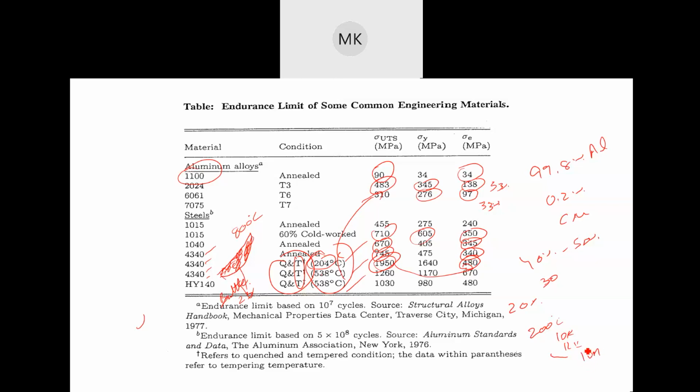The reason is that because of how hard these materials have become from quenching, any stress higher than a certain limit is going to initiate a crack. If it doesn't initiate a crack, it'll survive for a lifetime. But if it initiates a crack, it's going to fail. So that's why you have a very low endurance limit for these materials. But when you test it at 450 MPa, let's say, you can be sure that the failure won't happen. So that's the reason why lower temperature is bad.